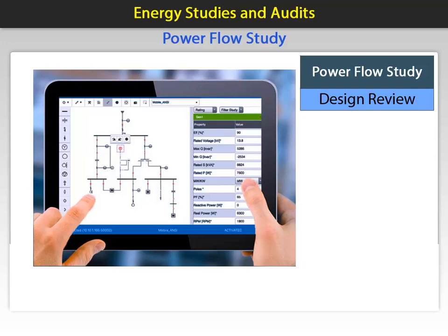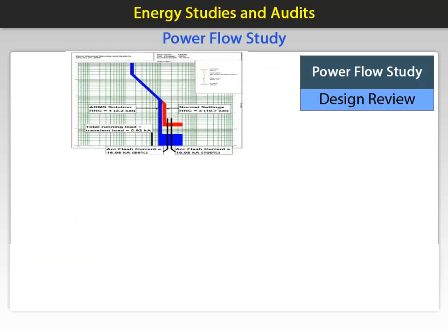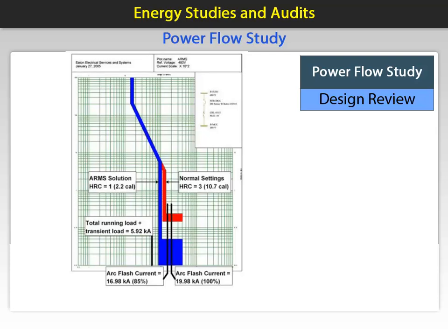It is also important to perform short-circuit and protective device coordination studies to ensure proper fault protection. These actions can provide potential solutions that include upgrades to outdated components like conductors, transformers, and circuit breakers. The review might also indicate a need to optimize system redundancy to improve reliability. One last outcome could reveal that the trip settings on certain circuit breakers be adjusted to ensure that the breaker closest to the fault trips first.